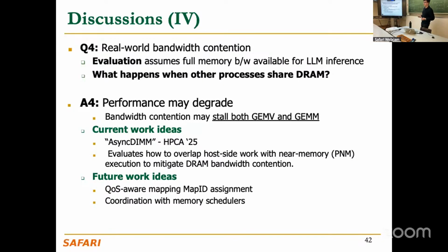There's also this coordination with memory schedulers idea that I had in mind. So here I do something like bank or channel aware placement, where I would extend the mapping selector to somehow know in real time the DRAM occupancy state and make some informed decisions based on this data. Basically, I'll put some PIM sensitive pages onto the underutilized channels and steer the SoC only pages onto other channels.